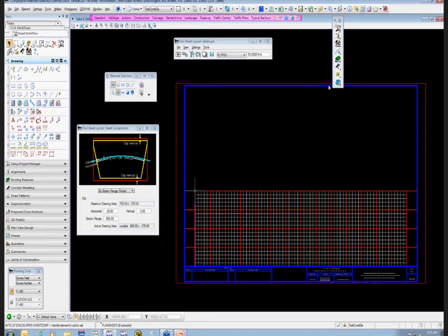The next thing that I need to do, and I'm going to delete my border real fast, is actually create the borders. I need to give it the job number, and I'm going to have 2 ports set up. I need to go in and give it the information. So this one I'm going to use baseline construction, tell it OK. And if I had a baseline that was running outside of my job, or it's not right through the center, that's where this offset could come in handy. You could move it one way or the other to shift the borders so that it's actually covering the design like it needs to be. If it's down the center line, you don't have to use an offset.